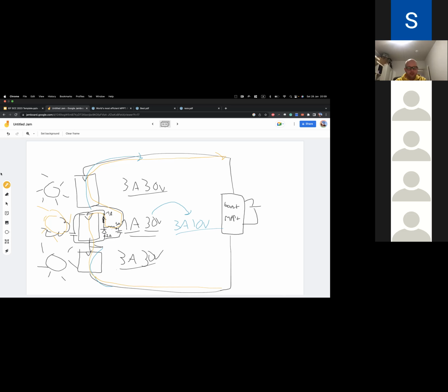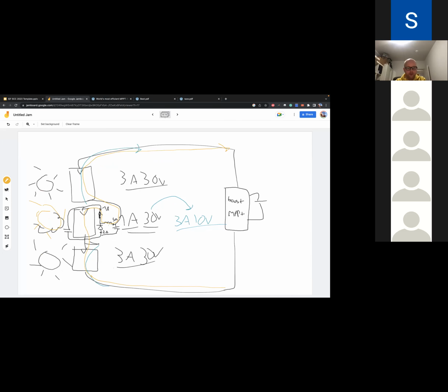The only downside is that you only turn this on when there's shade, and when there's no shade, you just leave the switch of the buck converter on. And then you do have some extra resistance in your string, but it's not much if you design it well. Wow. Could be a couple of milliohm.